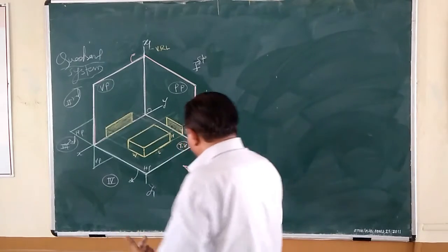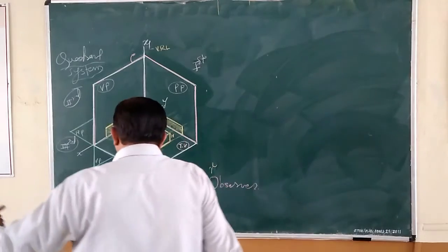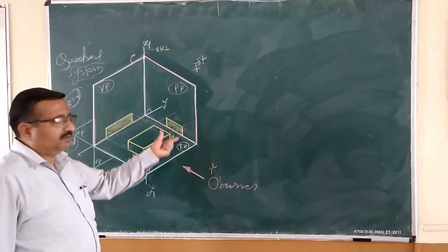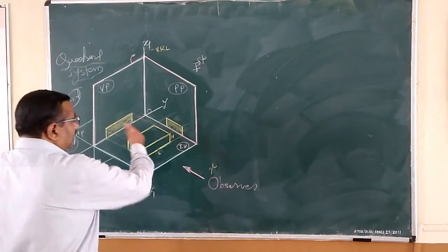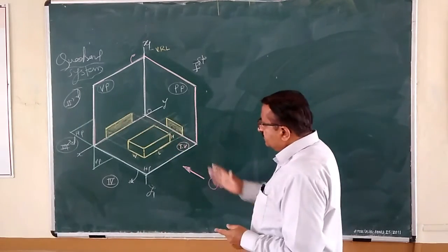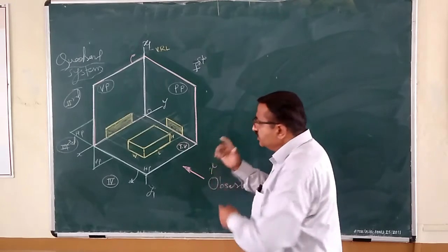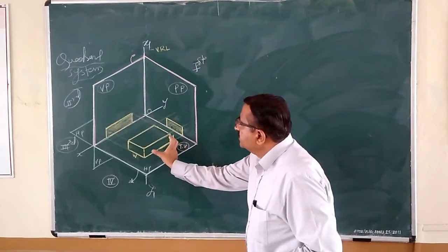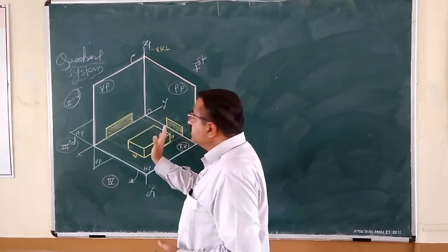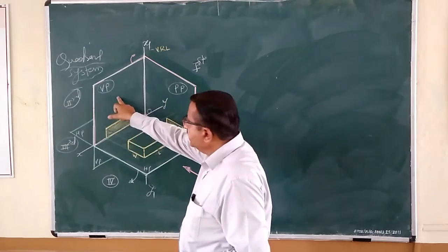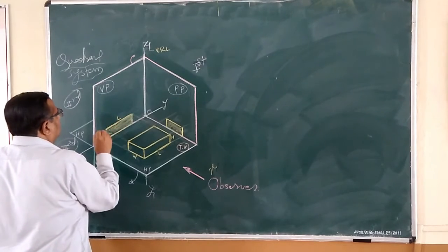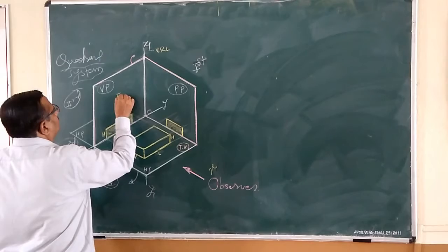In this case, as your right hand is busy with the construction of the front view, naturally the left hand is the reserved hand for the construction of the side view. So left hand side here, right hand. Now we have focused on this object by a torch in this direction. So naturally this L by H shadow of this surface will emerge over the vertical plane, which is just behind this. This is called the vertical plane. This view which carries length by height is nothing but its front image.